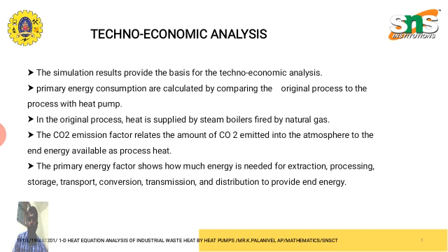Techno-economic analysis. The simulation results provide the basis for the techno-economic analysis. Potential reduction in carbon dioxide emissions and primary energy consumption are calculated by comparing the original process, with steam boilers fired by natural gas, with the heat pump process. The heat is supplied by steam boilers fired by natural gas. With the use of the heat pump, natural gas consumption is reduced, but electricity is needed for the compressor.